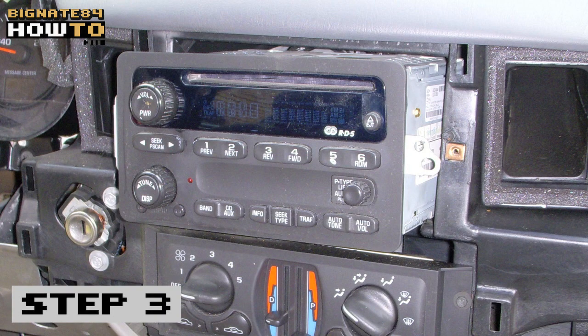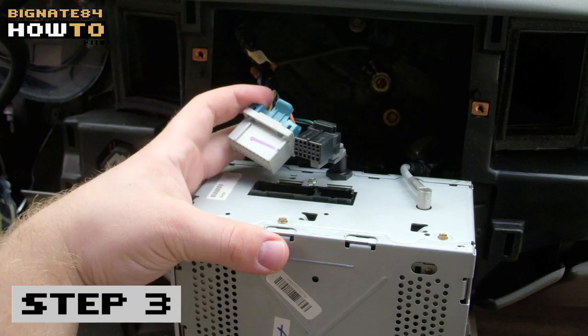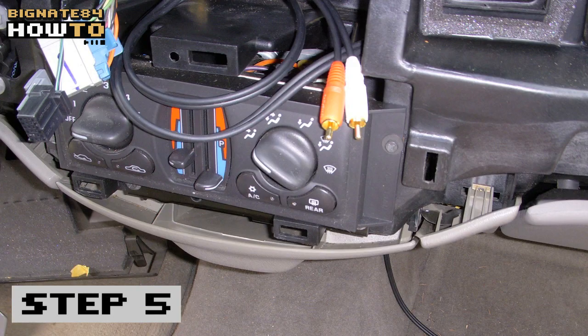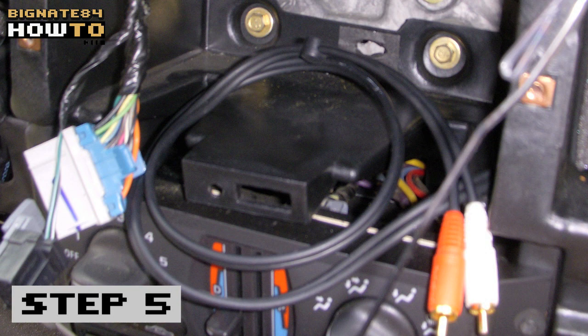Step 3. Remove the factory radio. Locate the anchor points, there should be at least 3, and remove the screws. It should slide out with a little finesse. Step 4. Unplug the wire harness and antenna. Step 5. Fish the audio cable. Use a coat hanger or fishing tool to run the cable from behind the radio to the ashtray.